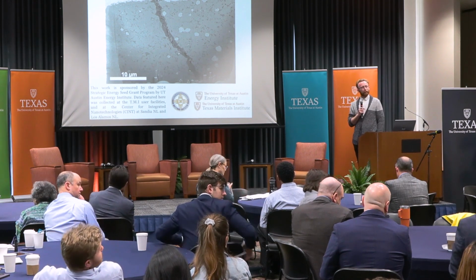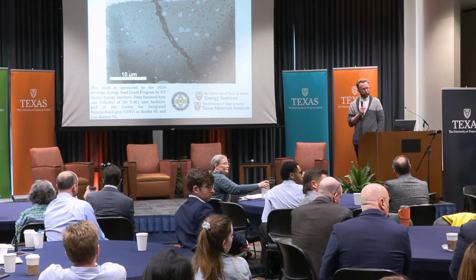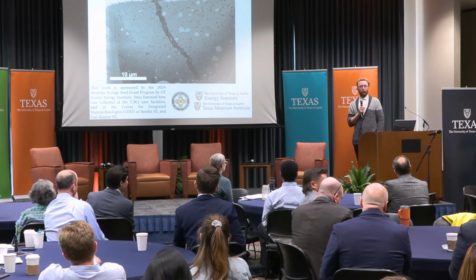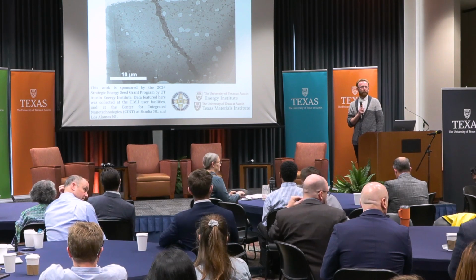So are you saying that this metal growth here is a failure for the material, or do you think that it's protective? It is a failure, yes. We are pushing these things until they completely fail, and this is a post-mortem analysis, I would say. Because as soon as that metal filament connects the anode to the cathode, electrons will flow through the cell instead of ions, which is the goal, and then you get no energy out the other side. Right. Okay, thank you.